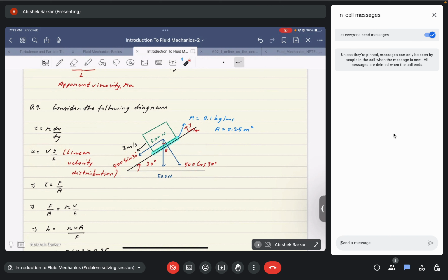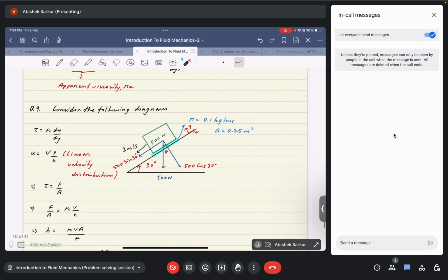If you are very talented in mathematics, you will just consider this to be a linear distribution and approximate it. But ideally this is found through the solution of a special type of flow known as the Couette flow, where we see a linear velocity distribution, and where one of the surfaces moving with a constant velocity is what drives the flow. Keeping that idea in mind, I know the velocity distribution, that's why I gave you the solution. You can still create your own approximations, but this is the most ideal one, so I have taken this, which fits in well with the current problem.